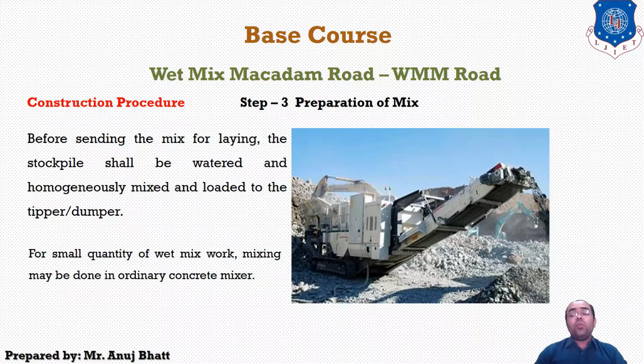In other cases, wet mix macadam shall be prepared in an approved mix plant with suitable capacity. In exceptional cases, for a small quantity of wet mix work, the mixing shall be done in an ordinary concrete mixer. But for larger work, you must adopt an approved dumper with sufficient capacity so that the laying procedure can be done continuously without any breaking.